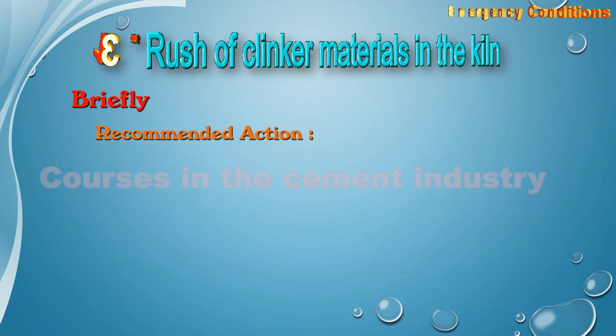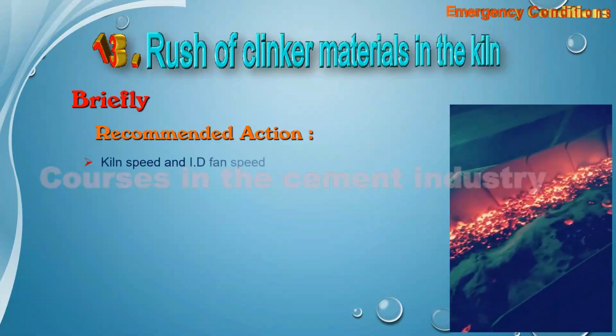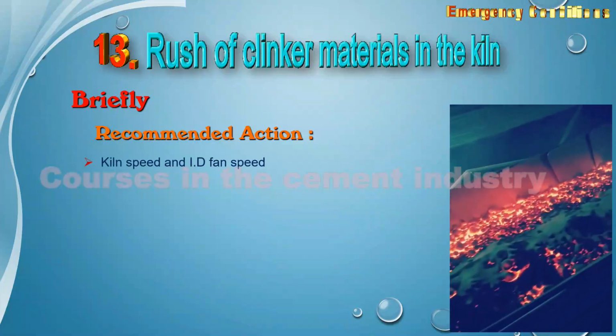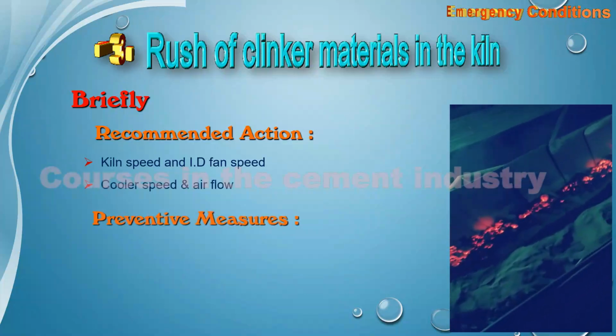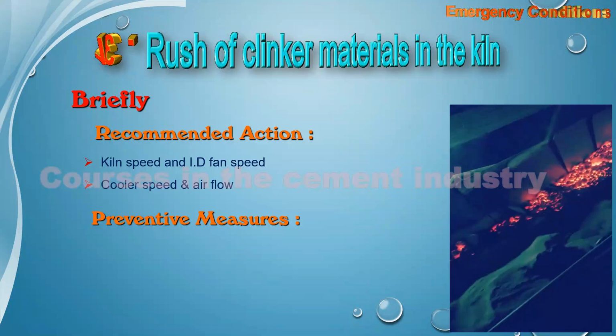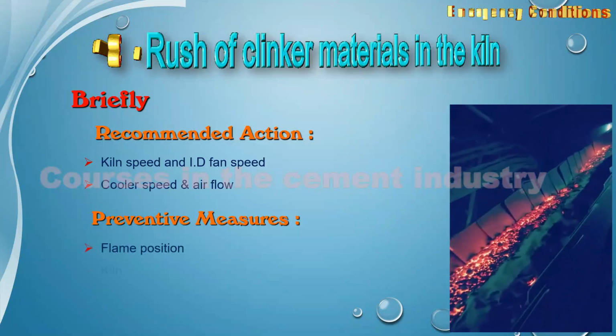Recommended action: 1. Kiln speed and ID fan speed. 2. Cooler speed and airflow. Preventive measures: 1. Flame position. 2. Kiln feed chemistry.